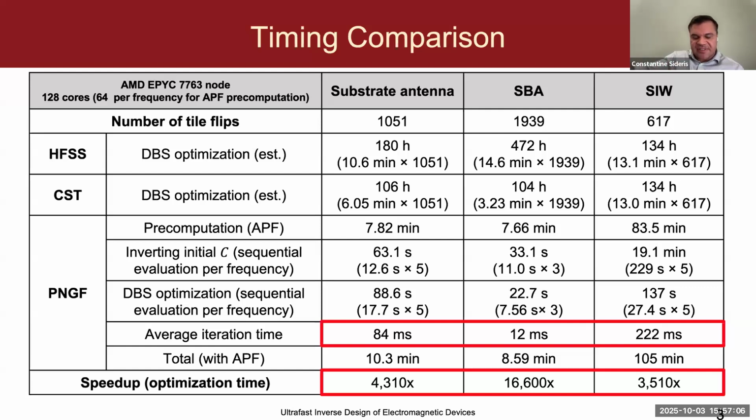In the simple example that I showed, we just did PECs, where we just have to satisfy the zero boundary condition. However, if you want to incorporate loss tangent, if you have lossy metals, you could simply treat them as dielectrics. The formulation does not increase in cost or complexity to use a complex epsilon rather than assuming that the conductivity is infinite. So it works just fine.